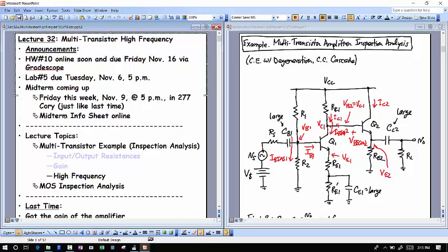Those are the main things we want out of this, that you understand what the differences were, what you had to do to design. So hopefully you had trade-offs you had to get around in your design. So you chose one value, then you found your gain is too high, your frequency is too low, and then you traded something off, and why is it that trade-off worked? The answer to that should have something to do with the DC biases around VCB, right? Those things that we talked about in lecture.